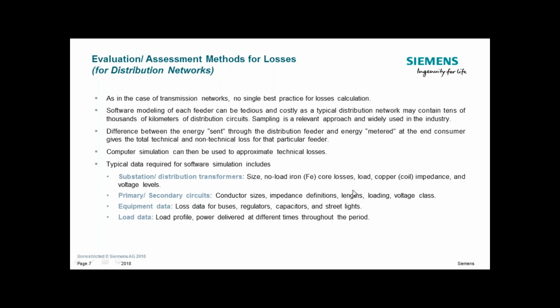That's the most important factor, which I can share with you, because now the concept of air conditioning is increasing. When you switch on air conditioning, it will not impact the transmission system, but in the distribution system, during switching on and off, it is treated as a motor. So these kinds of factors should also be considered when you are doing the loss calculations.